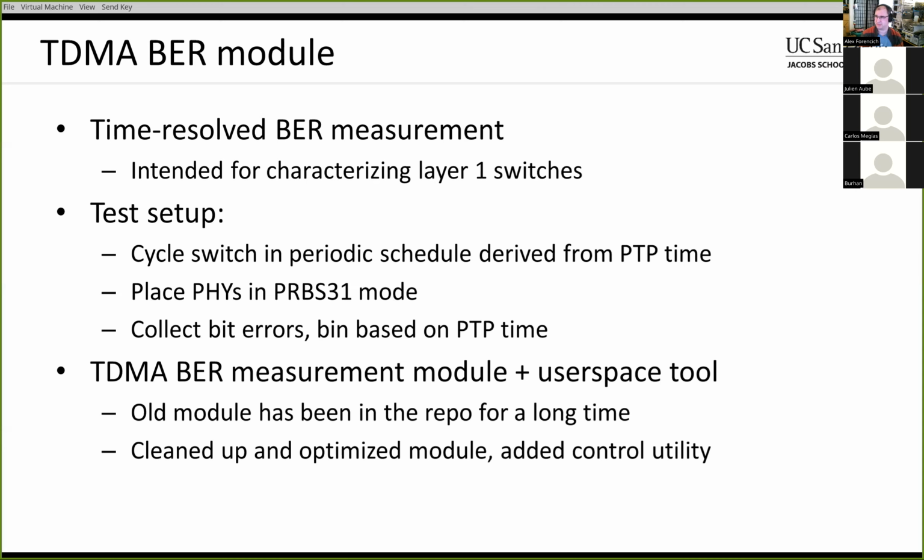Because if they're in PRBS31 mode, you can't send actual data. But if you look at things like the block error bit out of the PHY, then you might be able to do something similar, but online, because it'll work with the link working normally, but you can still collect some information about the link quality.